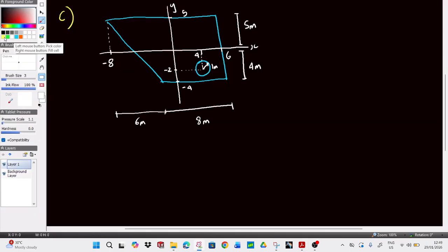So they want to find the moment of inertia of the entire figure with respect to the x-axis. So how do we find the moment of inertia for the figure? It is basically through the parallel axis theorem. So basically, the moment of inertia is just Ix equals Ix prime plus A dy squared.